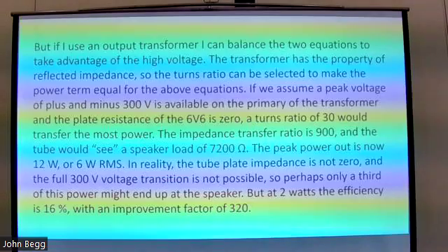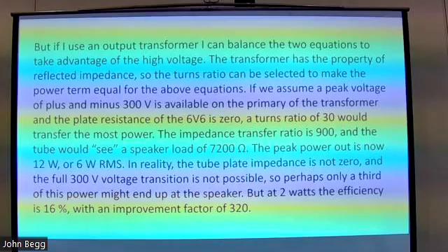But in the slide before, you shouldn't mix impedance, which is an AC parameter, with DC resistance, which is a DC parameter. Oh yeah, this is AC. No, because when you're talking about the power, you say I squared R, well, R is DC, we have to use the DC resistance of the voice coil, not the AC parameter of 8 ohms.